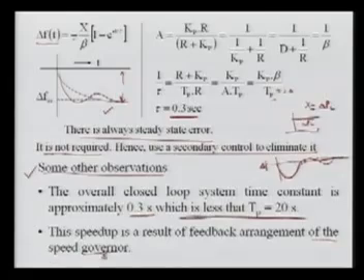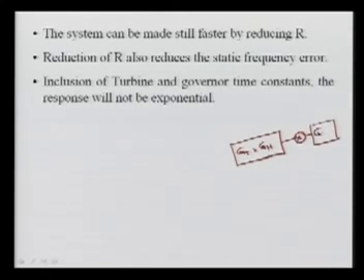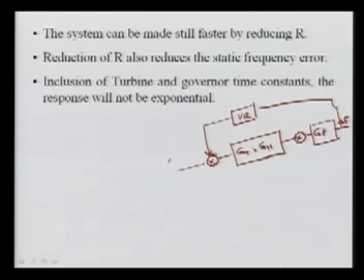For example, you can see here the turbine and governing transfer functions, GT and GH multiplied, and then GP, the transfer function of the power system including damping. Here is the change in f, which is fed back through 1 over R, and finally here is the change in PC, with this sign negative and this one positive.